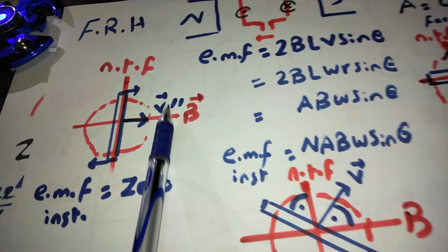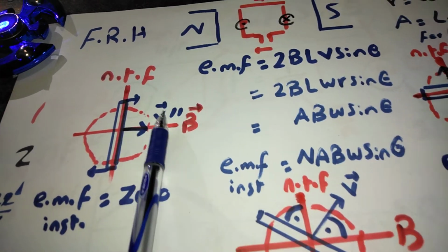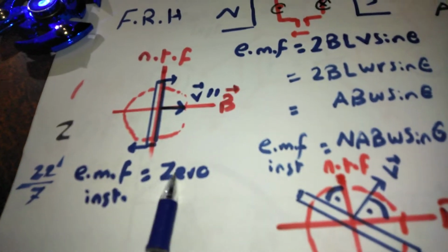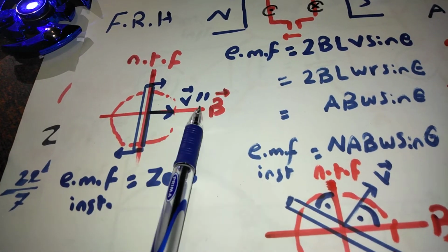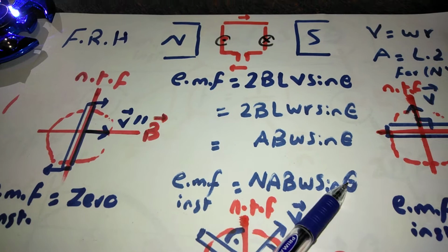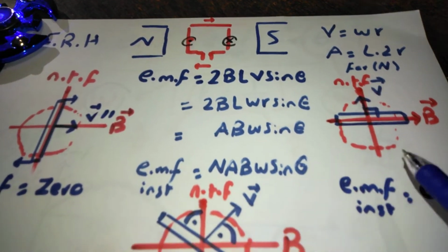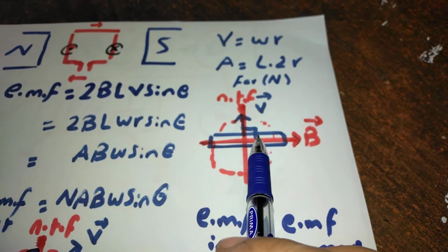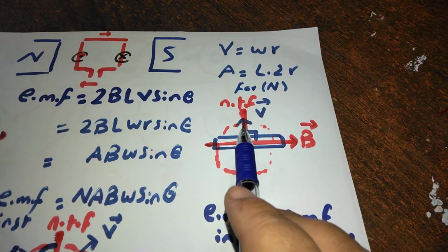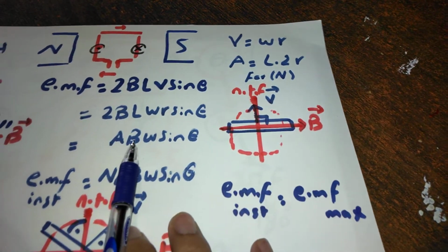So the velocity here is in one direction, normal to the plane of the coil, and here the motion or the velocity is parallel to the field and there is no output, as we substitute v parallel to B, so the angle here is equal to 0 and the output, of course, sine 0 multiplied by these factors equals 0. On the other hand, the parallel position will output the maximum value, when we can see that the normal to the coil, which is the velocity, is perpendicular to the field.